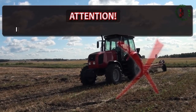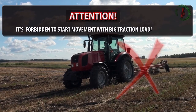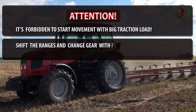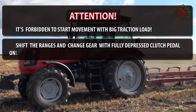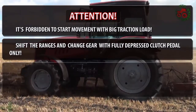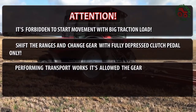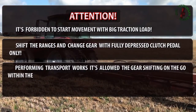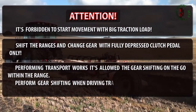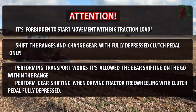Attention! It's forbidden to start movement with a big traction load. Shift the ranges and change gear with the clutch pedal fully depressed only. Performing transport works, it's allowed to shift gears on the go within the range. Perform gear shifting when driving the tractor freewheeling with the clutch pedal fully depressed.